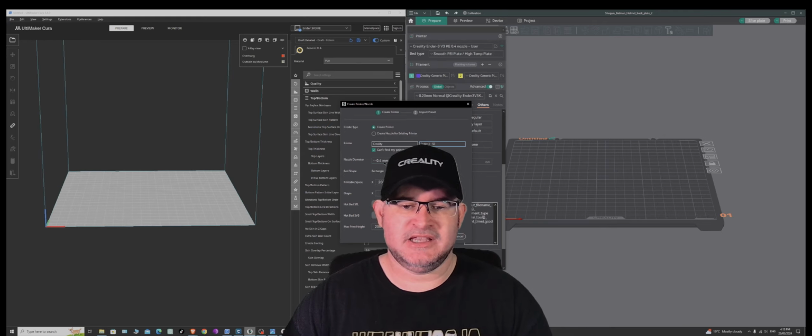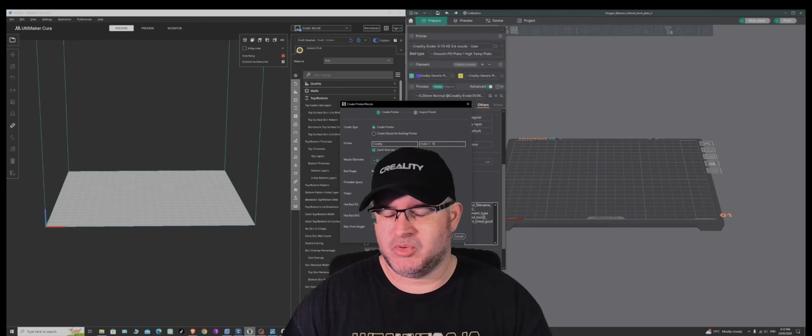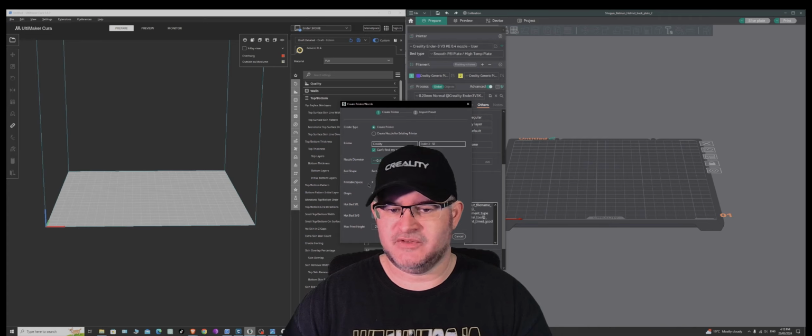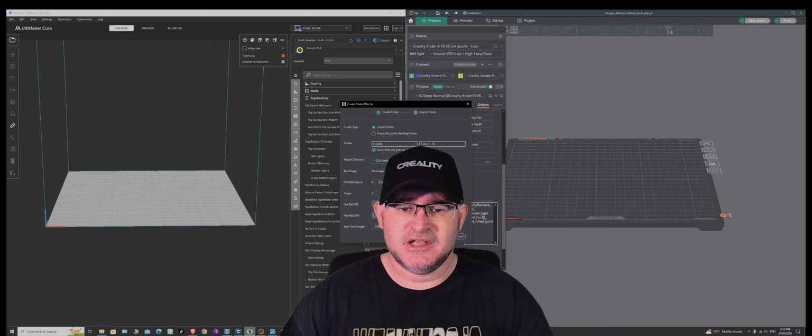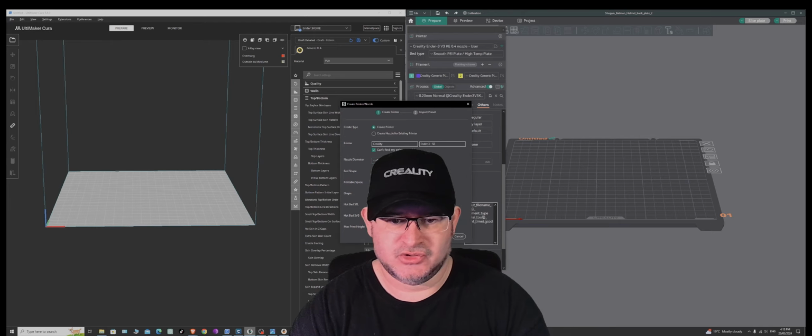Quite simply, easy. From there, you just select the nozzle type you've got, with your 0.4, 0.6, whichever one you've got, 0.3, 0.5, whatever you've got. And then you want to look at the dimensions. So it's asking you for the printable space, which is the bed volume. So that's the X and Y, which is the base dimensions. So for us, it's 220 by 220.